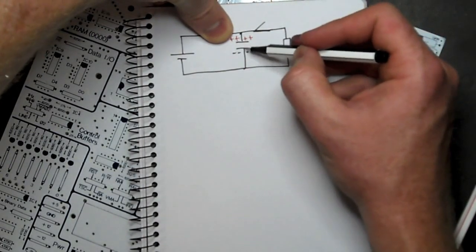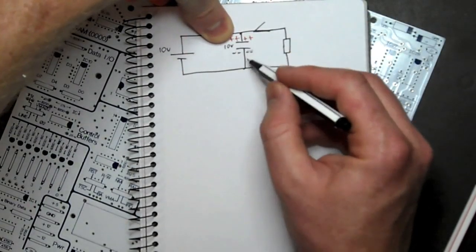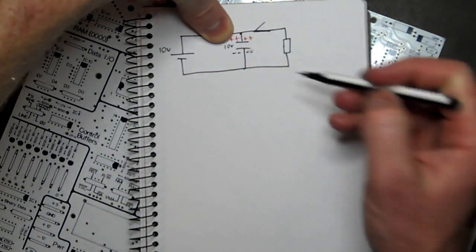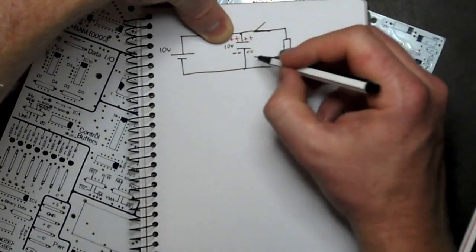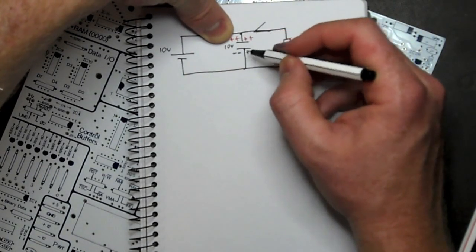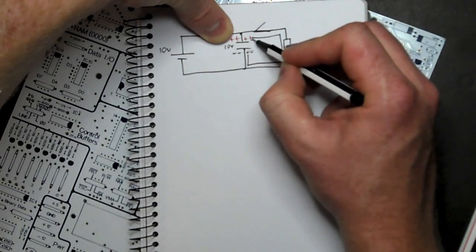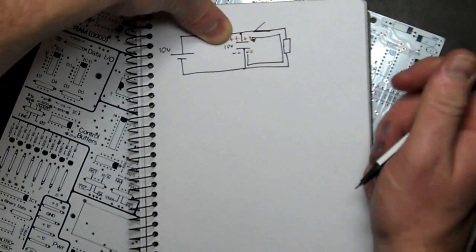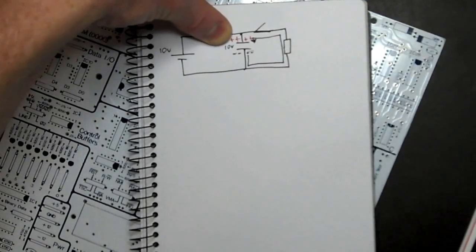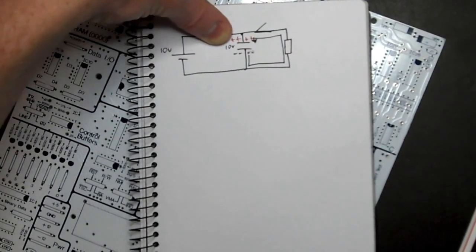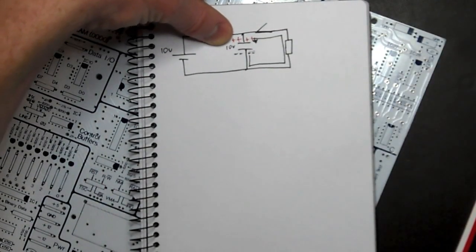I've got a full, let's call it 10 volts. I've got a full 10 volts difference between these two plates. So this now is acting as a battery for this circuit. So we've got negative down the top, negative down the bottom, positive up the top. We will get current flow from negative to positive through the resistor. Now, after a certain period of time, this capacitor will actually discharge. Just like a battery goes dead, the capacitor will lose its charge, and we will no longer get any current to flow in this circuit.